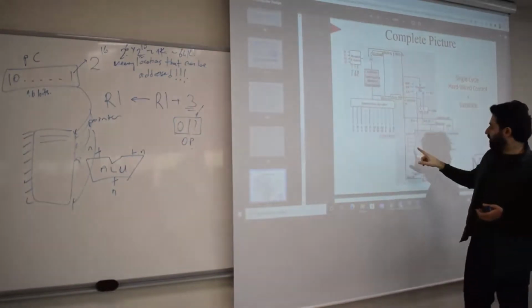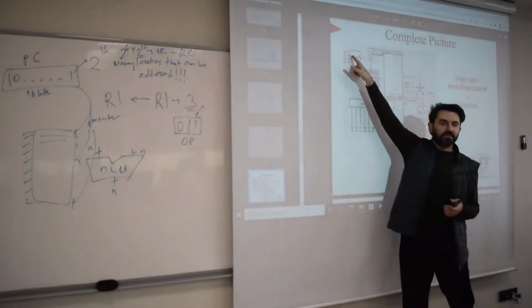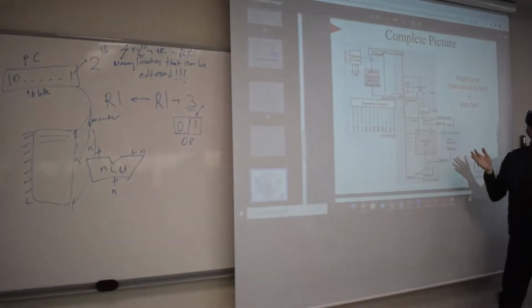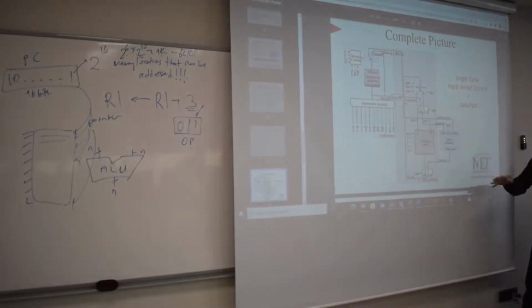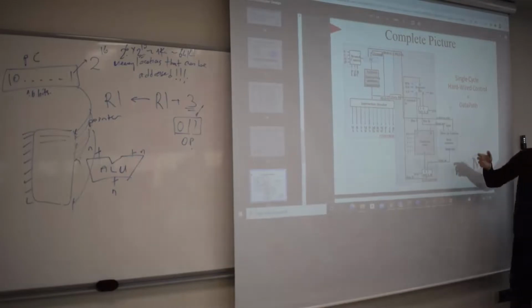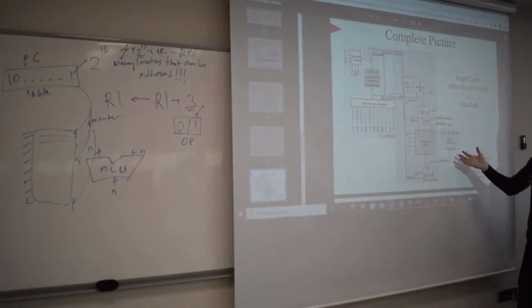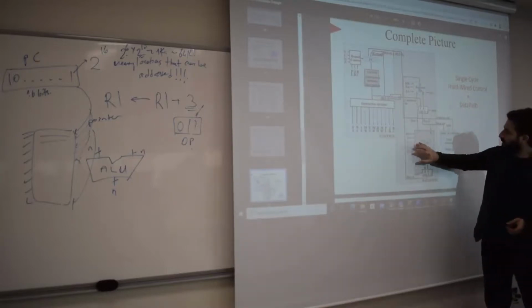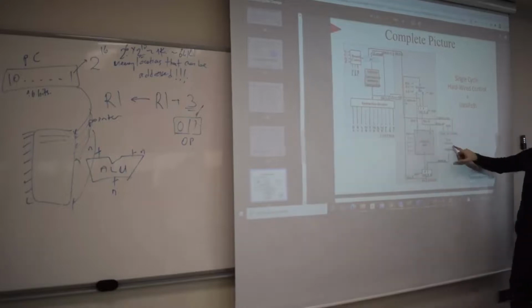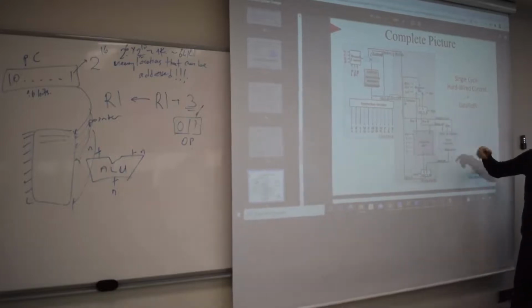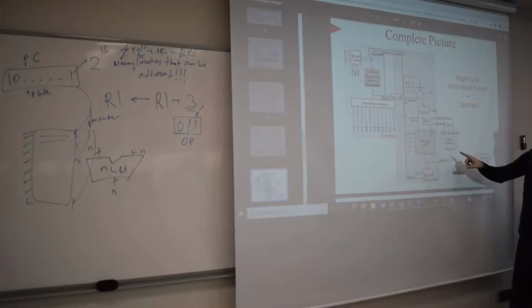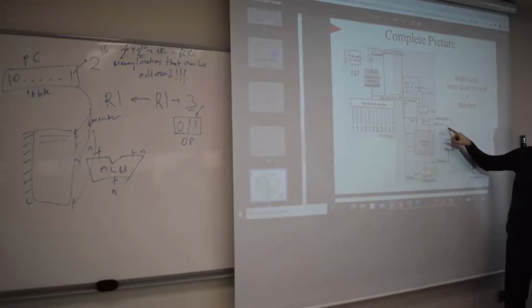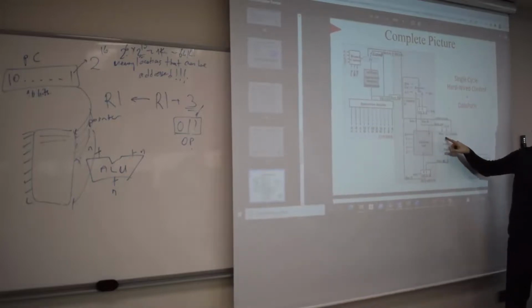You see, we didn't really wire them up because it's going to make it messy. You don't want your design to look messy. In reality, of course, you have to connect them. But in illustrations, we refrain from putting all these wires everywhere, so it's not going to look messy. So here, data memory is now here, you see? And one of the control bits that we were missing was the MW, that is the memory write and read control bit.